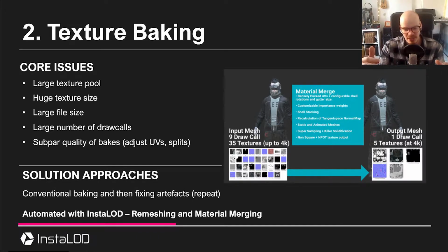Normal maps are typically baked using 16-bit textures, and that is typically a requirement for them to look good, because we need that additional information in those textures to generate good shading. If we were to use 8-bit normal maps, we could get texture banding, or that typically does occur then, and that looks pretty ugly. It's quite visible. So that is why we typically stay away from 8-bit normal maps.